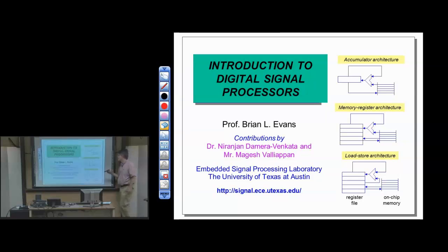So in this particular architecture, just to get some graphic notation here, this is the on-chip memory on the right. Local on-chip memory is high speed. The throughput of reading and writing to local on-chip memory is the same as the CPU clock, or the instruction cycle time, to be more precise. But on-chip memory was limited, and it was also dual ported, so you could do two reads in one memory cell at one time. So it was special purpose memory.